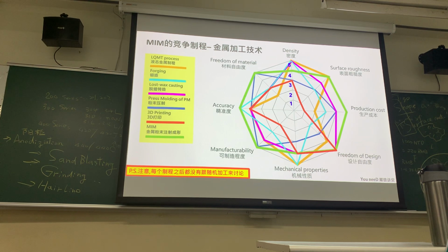The easy way to think about it is to use a mesh. With different meshes we can make different ranges. We just need to control the range. But a mechanical mesh is not so good. Why? Because when the powder is very small, it will fly. So we can use an air mesh, an airflow mesh. The airflow mesh is very popular in industry.